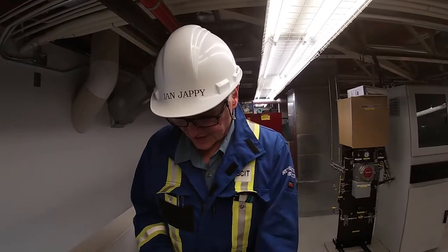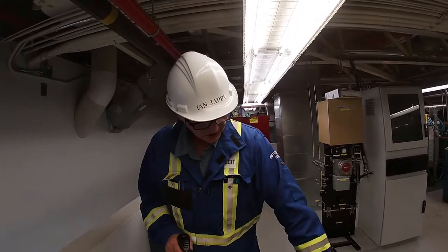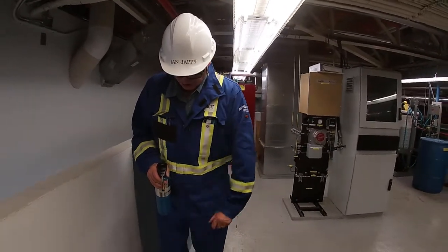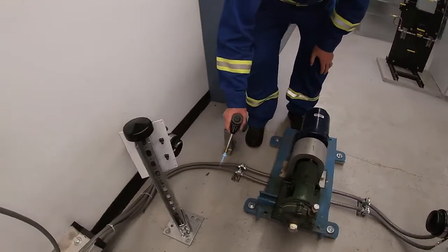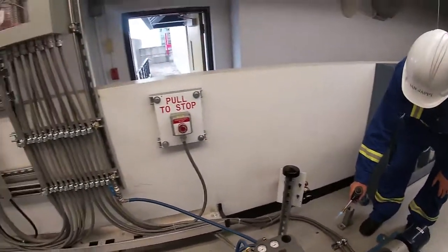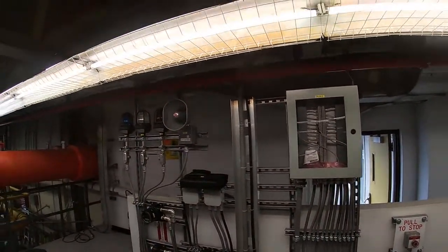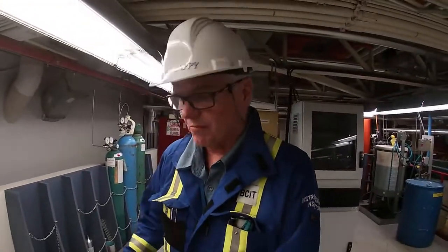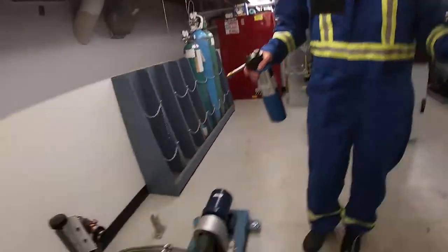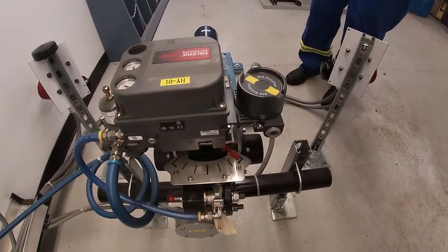Okay, so now we're going to test the other IR scanner. So I've got the cover on GT3B, this is GT3A, and we'll see if we get our horn and strobe. So we've annunciated our horn and strobe, and we know that the 1 out of 2 voting works for the horn and strobe. Let's see what happens now when we have both of them pull in.